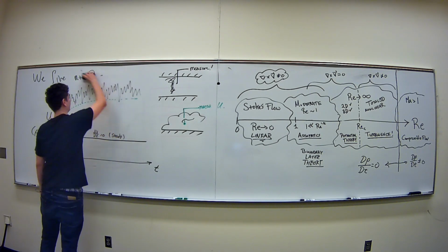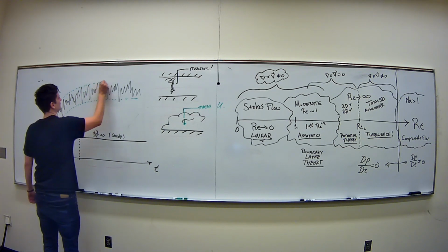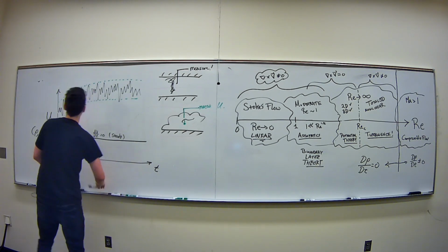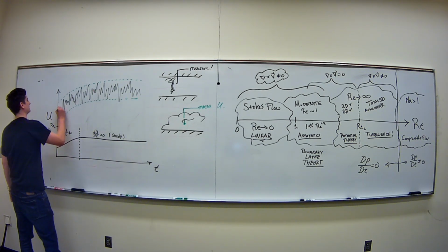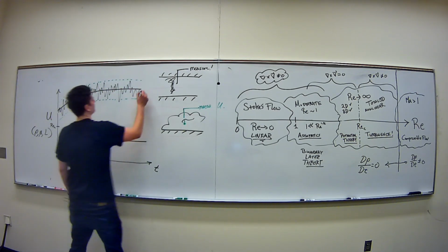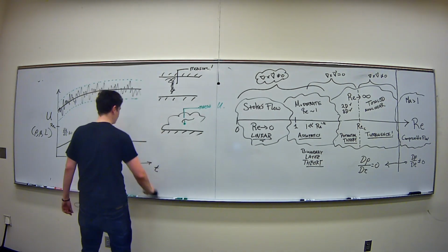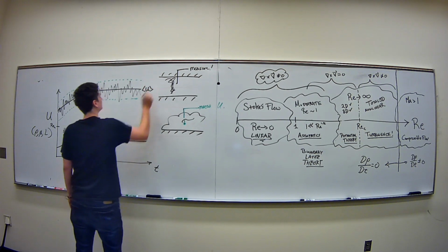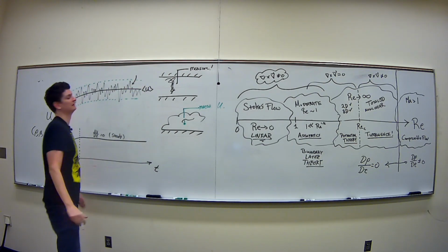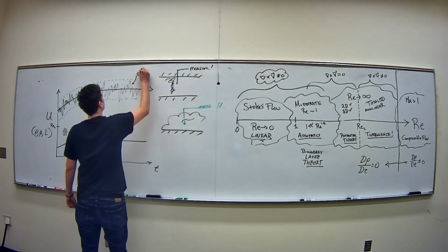Your sense of an average comes from some envelope this stuff exists in. Everything we're talking about is qualitative right now. So you see what I'm saying, and that mean is found as some best fit line existing here. In the theory of turbulence, you need to have some sort of mean flow, which we'll call this. And then you also have the instantaneous, where you have this fluctuating part about a mean. And that is a U prime.